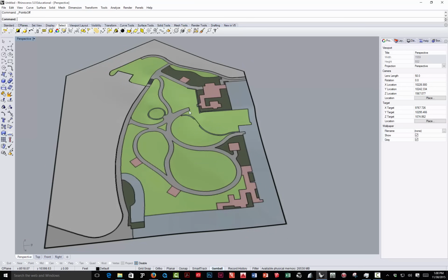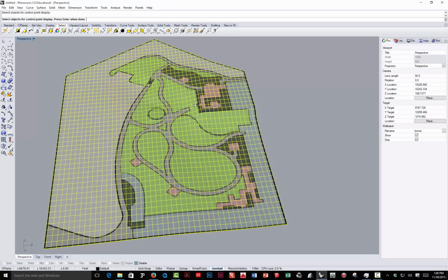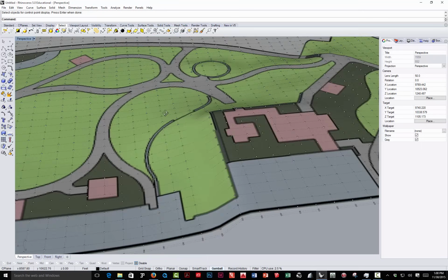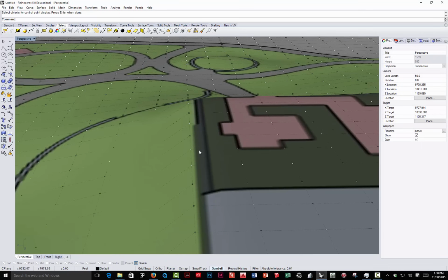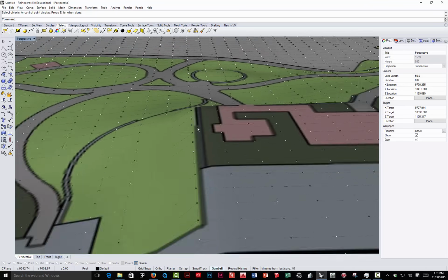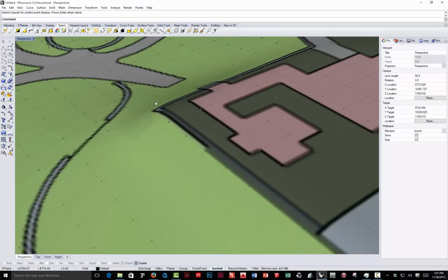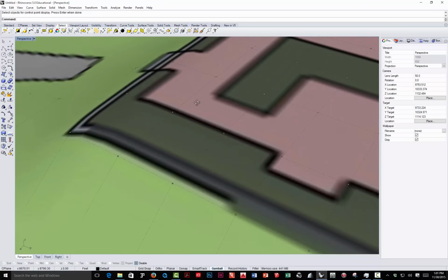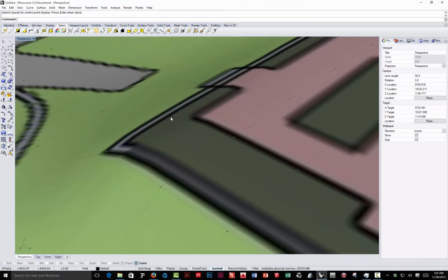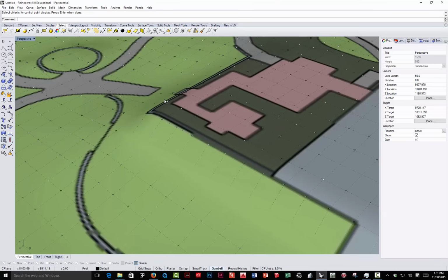And so before I drop that in, I'm actually going to turn the show points back on. And what it would really be nice to have is a set of control points just inside this side of the wall, and one just along the wall here. So I could have the wall at the proper height for the upper side here, and then I can take this set and drop it down and get the wall for the second height. Now if I move these over, that kind of creates problems on the grid for me. And same thing here on the other side. I really would like to have a set of control points on both sides.